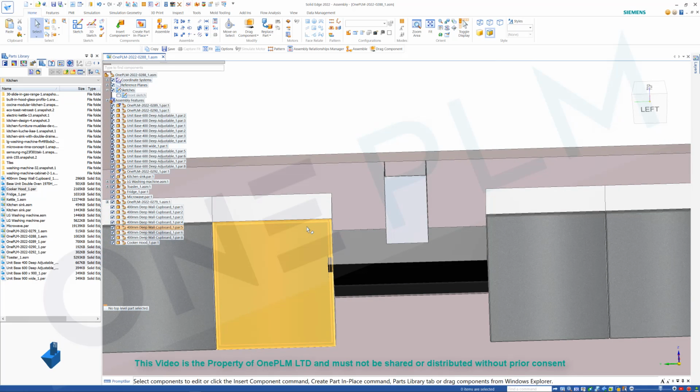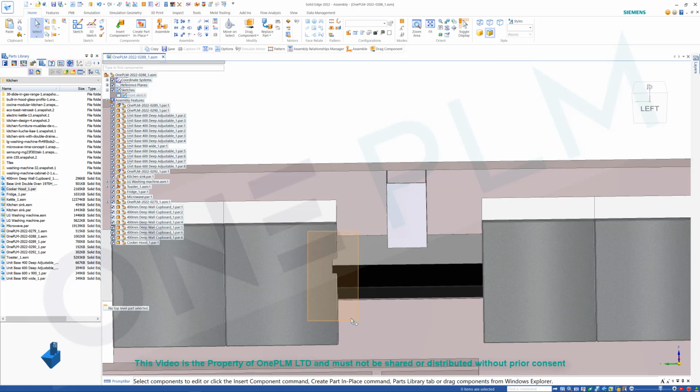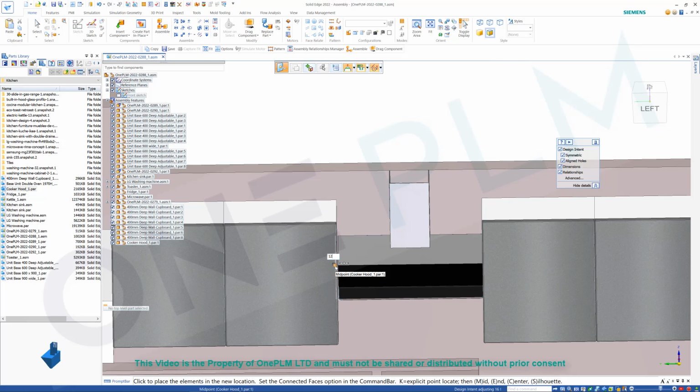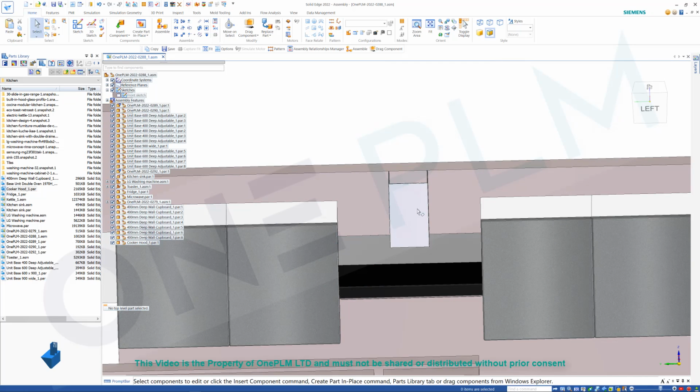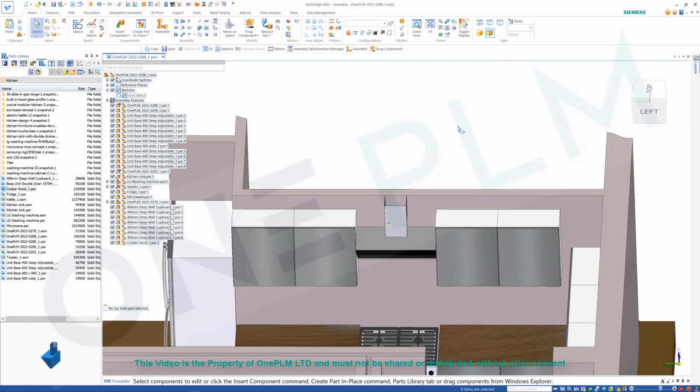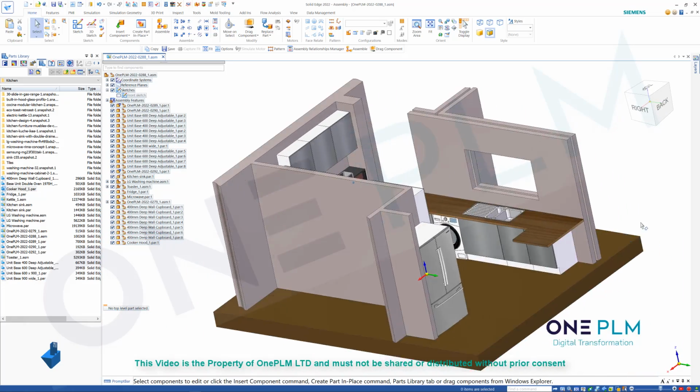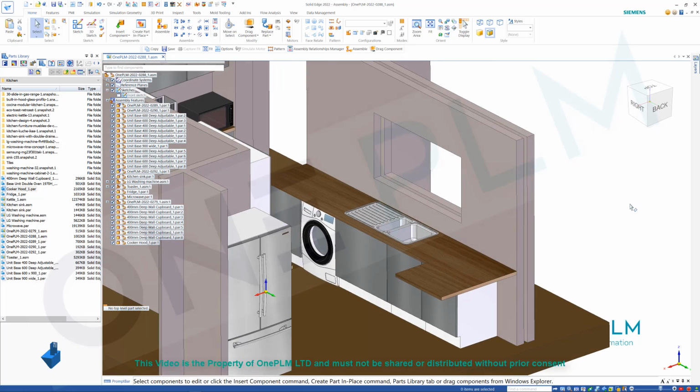You can see that we actually needed to go and select all the faces to make that smaller. And I think it needs to be 25, so because it's symmetrical, I need to go 12.5 on that. And that's looking pretty good now. Okay, so we could go and do more items on here.